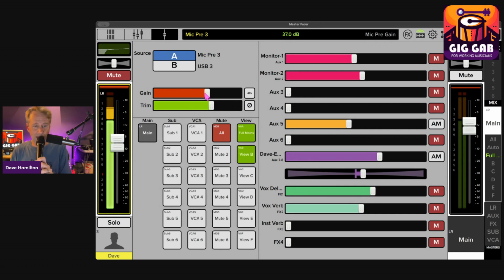So I try to get this on this Mackie mixer. I've found that I can really get things nice and smooth and have a lot of control down the chain if I'm right about at the cusp of where it just goes above unity, to maybe 1 to 3 dB above it. Not every mixer is going to be the same in this regard. You kind of need to experiment and listen, use your ears in addition to your eyes. I think both your ears and your eyes are important when setting up a mixer. So use your ears and your eyes as you're setting gains.